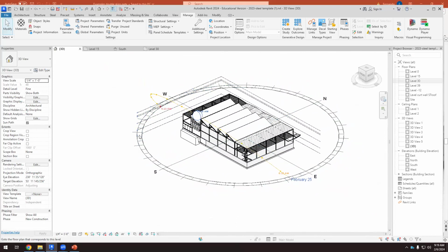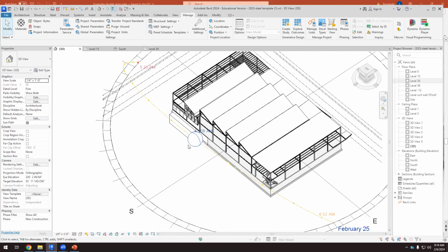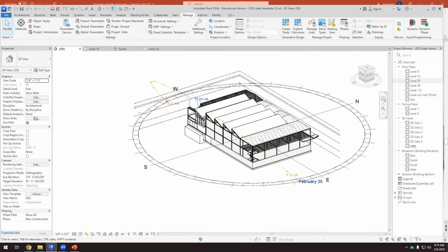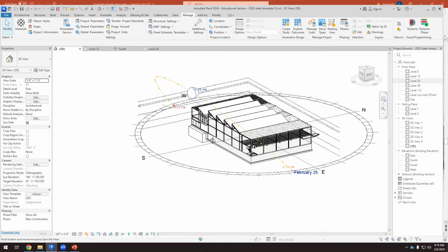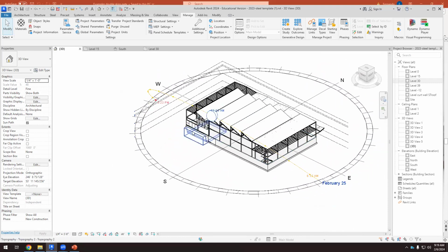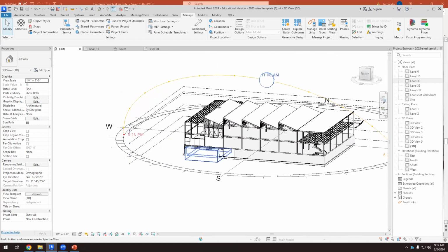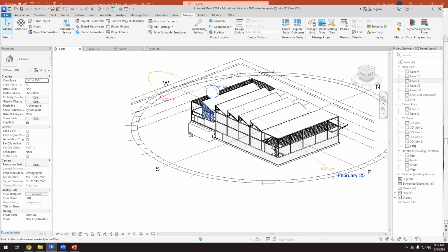So that's useful, especially when we're working with orientations that are not aligned with this vertical axis, northwest. But remember that if we have made a mistake with the orientation of the building, because we started drawing without taking into account the north of the building, we can always work with the true north, and then we can rotate the true north. And now this is the south facade, it's not the north. Why do I want this to be the south facade? Because all these things that we are doing here make sense if we are working in the south elevation.